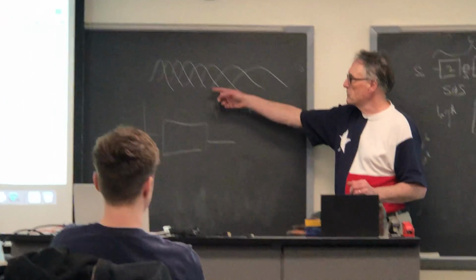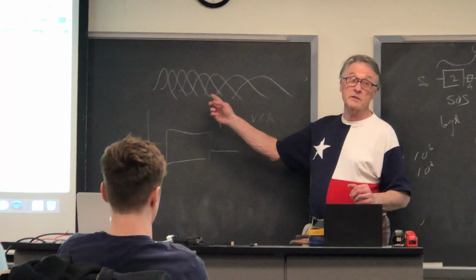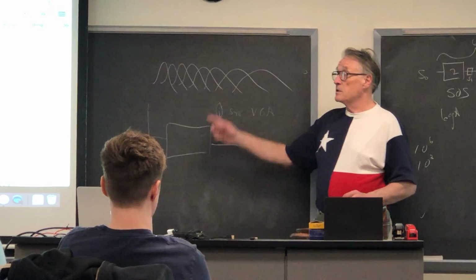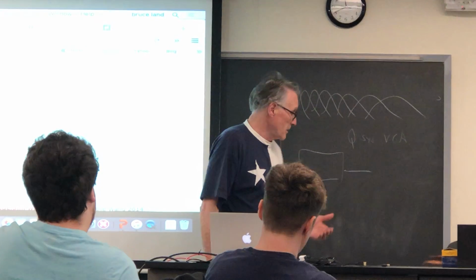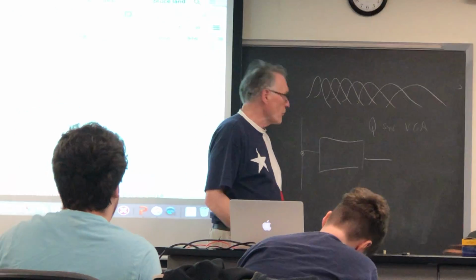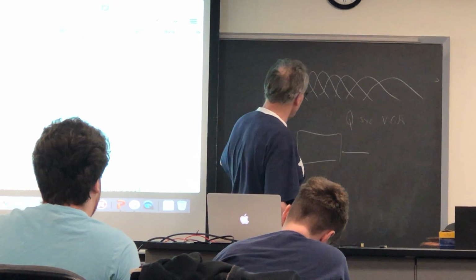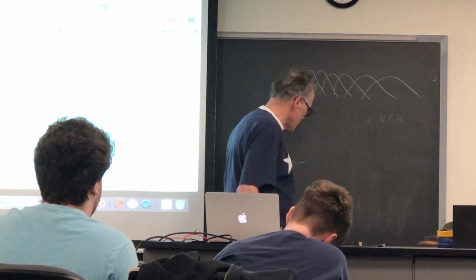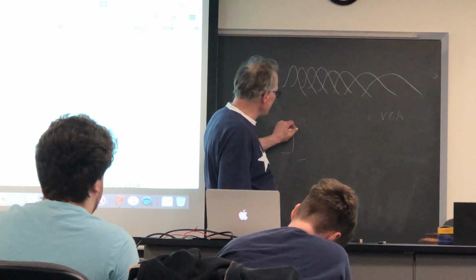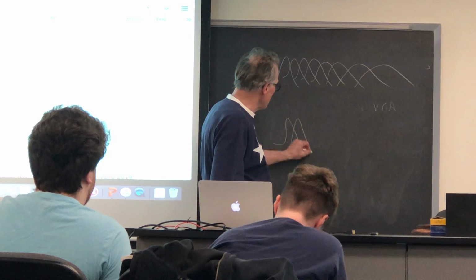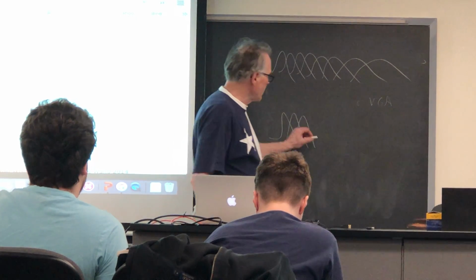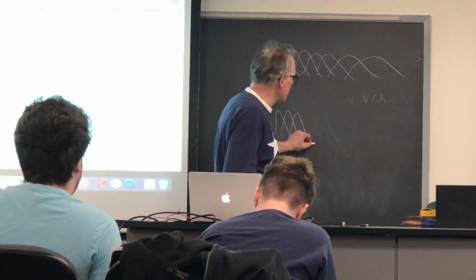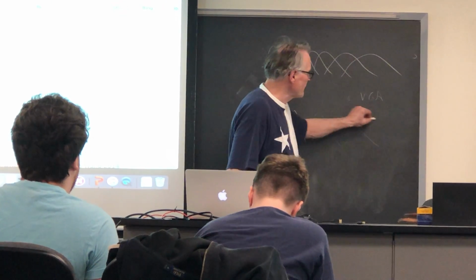This is particularly useful for speech analysis, because the way you perceive speech, the way you perceive sounds, is approximated as a group of filters whose spacing at low frequencies is linear in frequency and with constant bandwidth, and at higher frequencies becomes a broader distribution of frequencies.